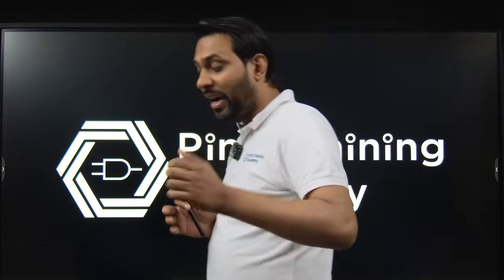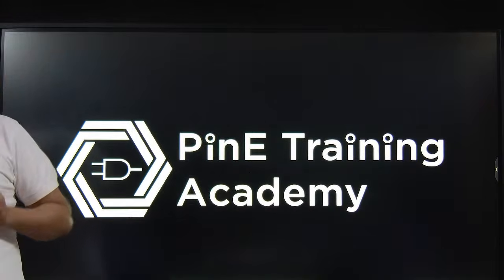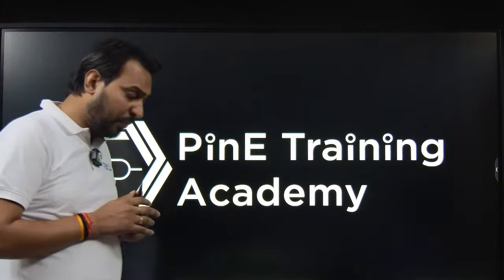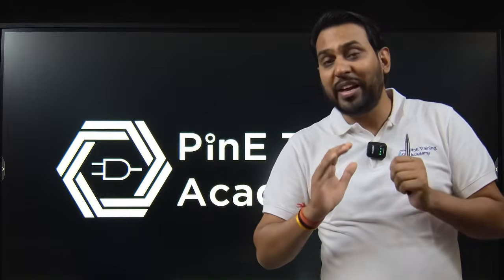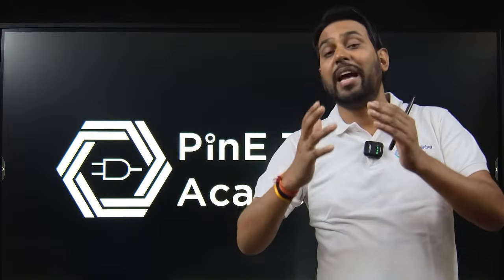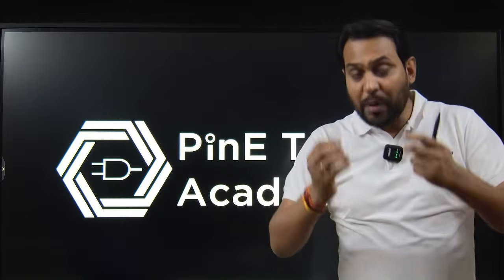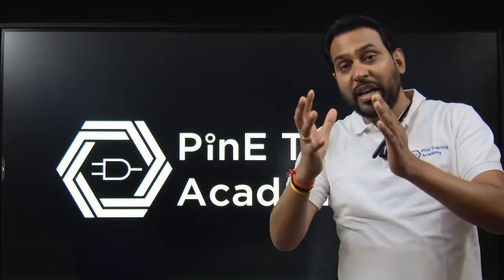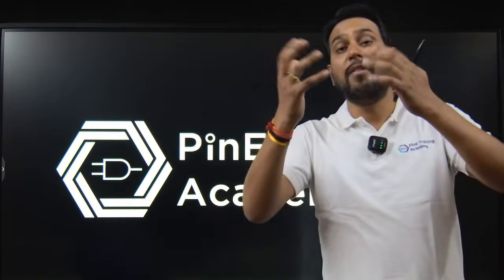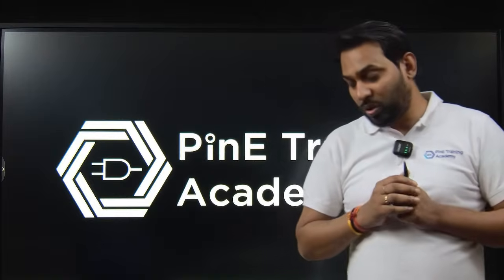Then we go to the third class. In the third lecture, we discuss dependent sources and independent sources. That is very important. Whenever you talk about amplification, we cannot amplify with the help of only resistors, capacitors and inductors. We require another circuit. So how can you convert your circuit in this way so that it behaves like an amplifier? That is where we require a dependent source.